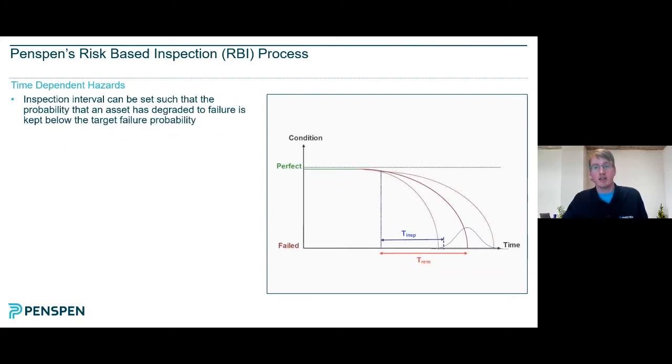So essentially then, if we have that information available, what we can do then is assign an inspection interval that allows us to go back and confirm the condition of our asset before we reach that point where uncertainty is such that the risk of the pipeline having failed is greater than the tolerable level. Of course, we want to set this inspection interval at a point that gives us time to act on what we find. And what that information then allows us to do is to go back, accepting that risk assessment and integrity management is an iterative process, and feed back the findings from that inspection into our model and potentially refine the model and whereabouts we are on that failure curve over time. And then that allows us to then determine when the next inspection is due.